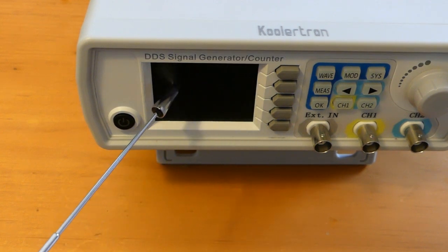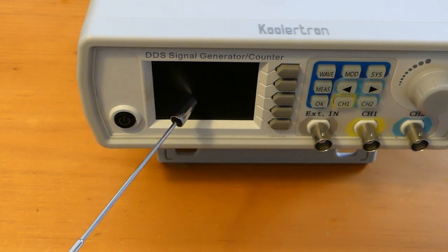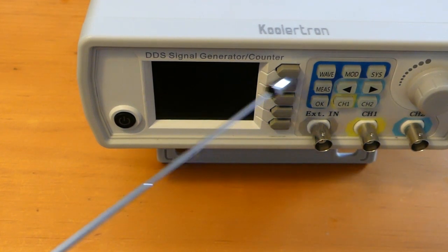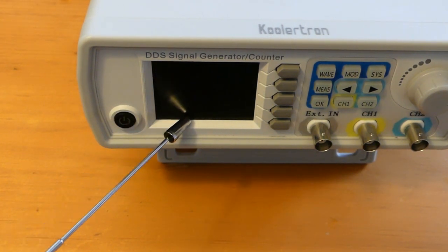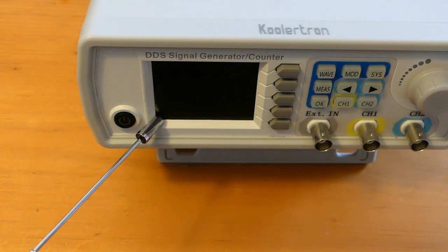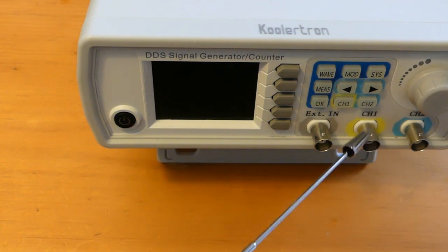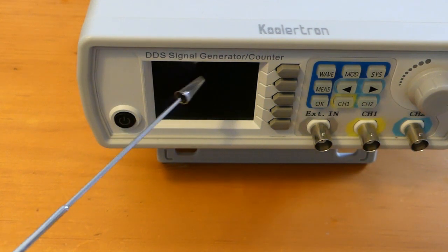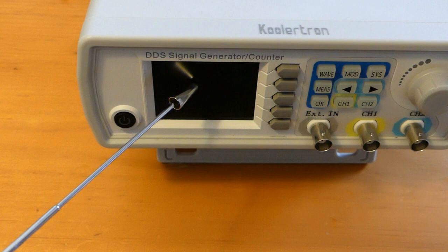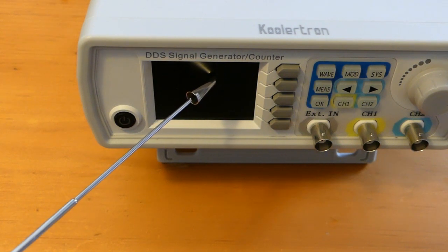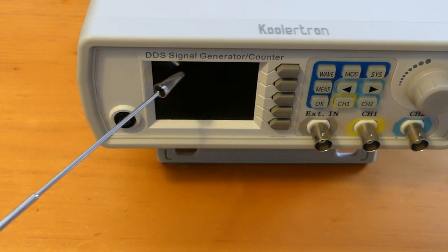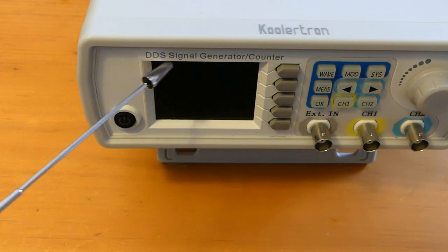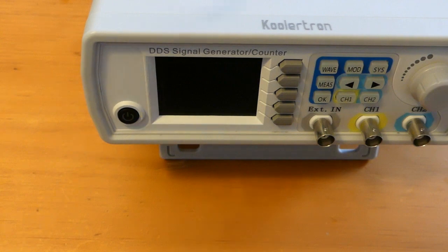The reason is that this device shows what's called the open circuit voltage. So when you put this output on a 50 ohm load, it's not really getting 3.2 volts peak to peak, it's really half of that. So if you want the output of this guy to be 7 dBm or 8 dBm, you want to set the voltage peak to peak here to be 3.2 volts peak to peak. Alright? And then obviously you set the frequency to 7200 kilohertz. Got that, folks?